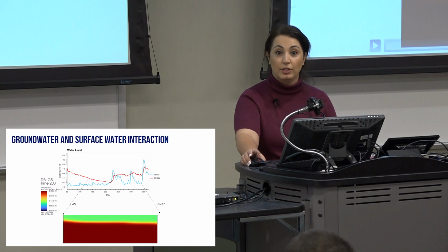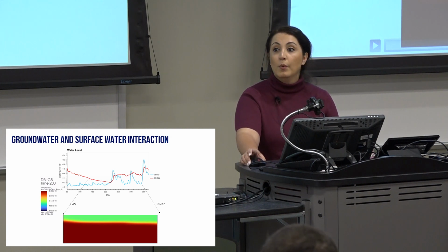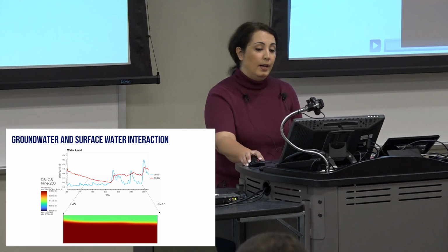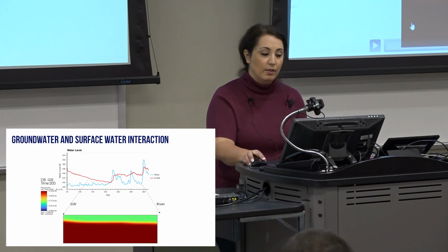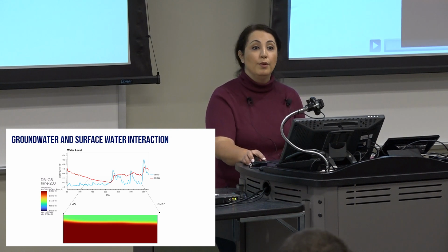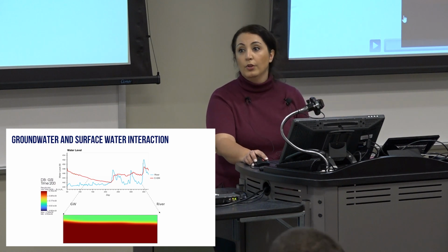What if it is fractured? What if we have some inclusions in there? We will not have the same thing, and who knows whether that is homogeneous or not. So for me, the question is, if we have those fractures, and this length of simulation is 100 meters, will we see the breakthrough of arsenic farther in the groundwater model or not?